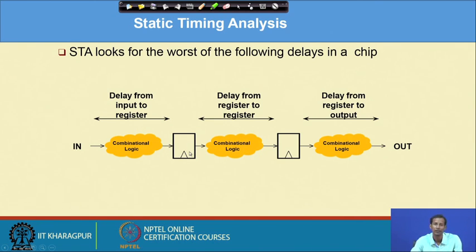now clock dependent. Clock dependence means, in a combinatorial circuit, if I change any of the inputs, the output automatically tries to change, or the corresponding logic elements start their operation. But in a sequential element, unless you find the edge, if it is edge triggered, it will not start its operation.